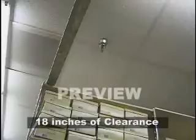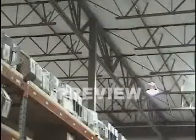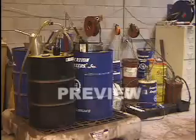The same applies to automatic fire sprinklers. They must have at least 18 inches of clearance to function properly in the event of a fire. It's not just good housekeeping, it's the law. It's everyone's job to help keep the work area clutter-free and safe from other fire hazards, such as improperly used or stored chemicals, which we will cover in a couple of minutes.